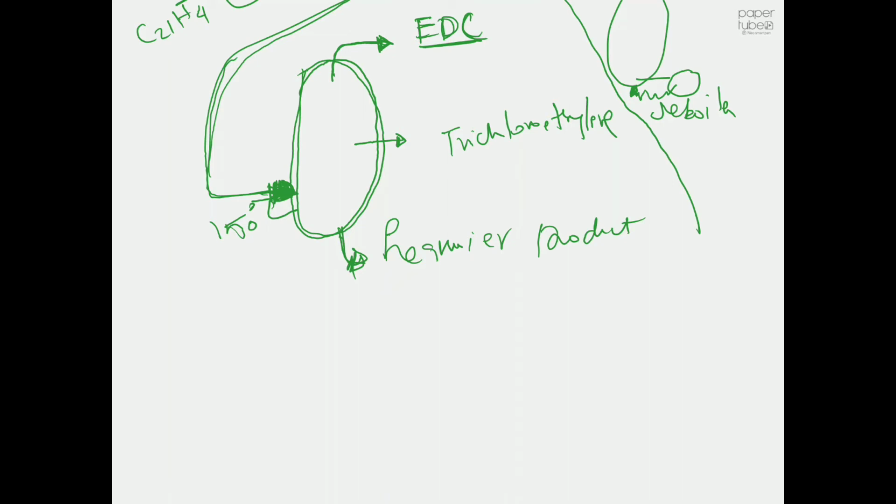So the whole idea is that we can connect this stream to a distillation column, and this heated stream itself will act like the reboiler of the distillation column. So we can design such an equipment, why not? But for our project, or for our design calculation, we are going to stick to the low temperature chlorination, and the justification for selecting low temperature chlorination is its very high selectivity towards ethylene dichloride.